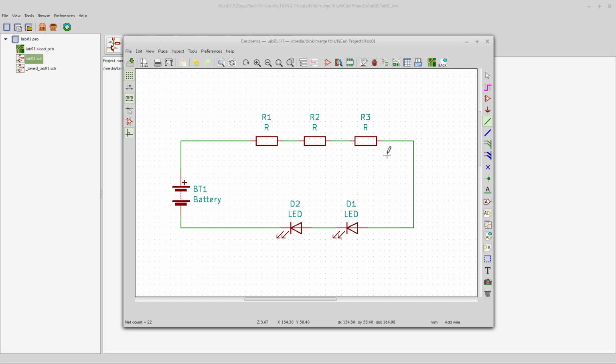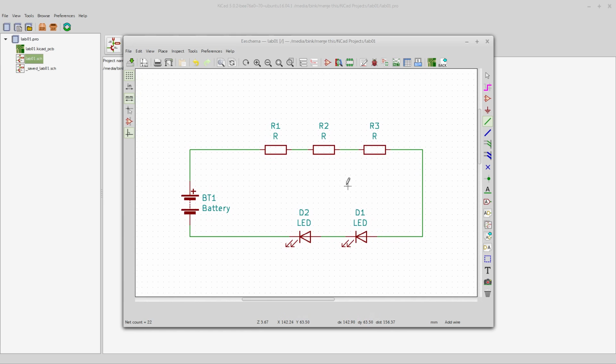No, not quite yet. So now we have to associate these footprints here with a real life component, right? I just called them footprints again. These symbols need to be associated to a footprint, and the footprint is going to be the electrical pads and the shape of the actual product we're going to use. So this is where everything takes a hard turn. It's not good. So you are going to go assign PCB footprints to a schematic symbol.